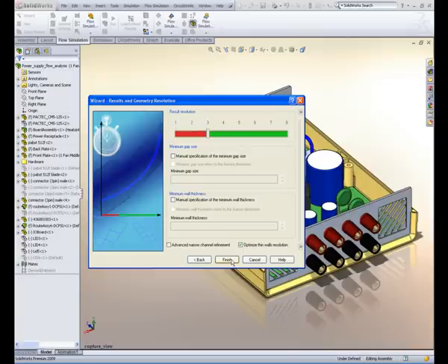Here we will accept the default atmospheric pressure and room temperature. And finally, we consider refining the solution around areas of our model that may have small gaps and thin wall components which are surrounded by fluid. In our model, we don't really need to worry about these kinds of features, but if we had, say, a tiny nozzle through which our fluid passes, or a thin baffle held in the flow stream, then we can highlight their relative dimensions to make sure these fine features are properly considered.